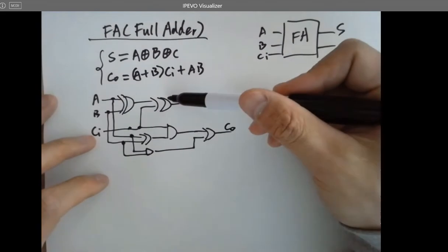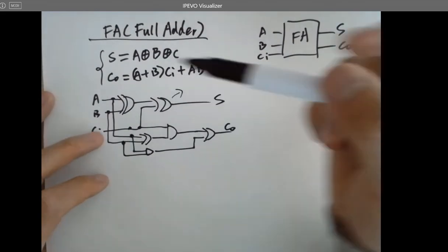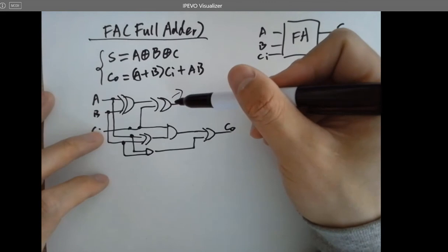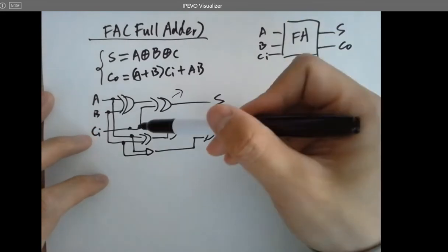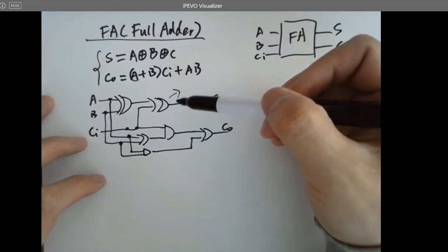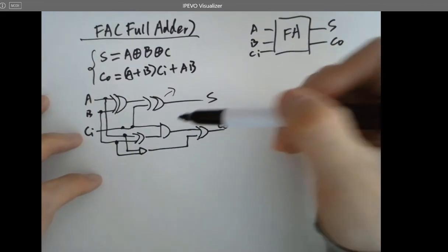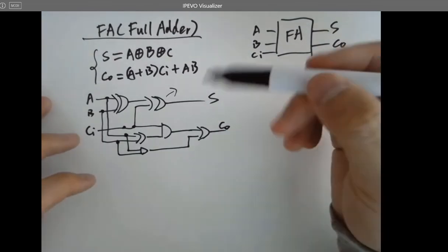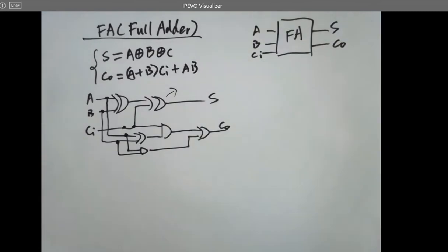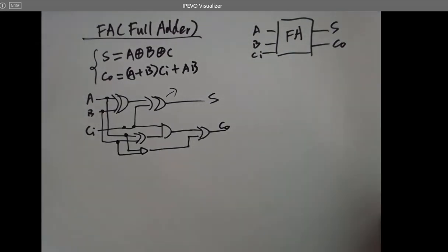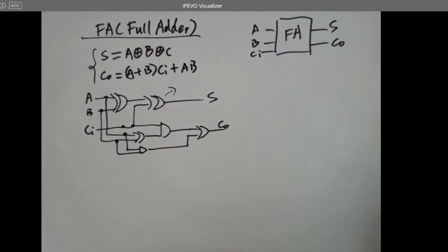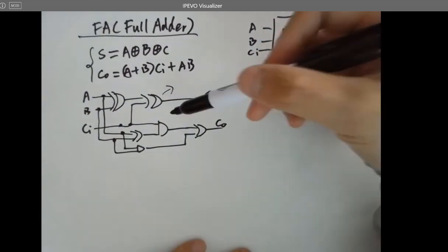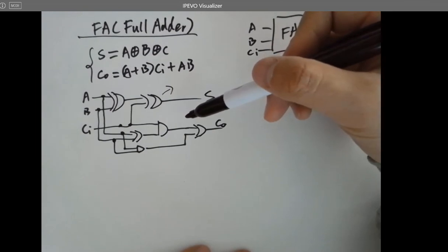And every single XOR gate has a lot of gates inside as well, if you do not use AOI logic. So this slide is actually huge. If you have a lot of transistors inside, a lot of traces, the problem will be time delay, because you have so many parasitic capacitors inside. There are traces, and because all the circuits are built in the silicon wafer, there will be dielectric materials. All these gates have oxide in the middle, so they have capacitance. And it's going to increase the time delay for the signals. So this is actually really slow. It's a slow design. It's not ideal.